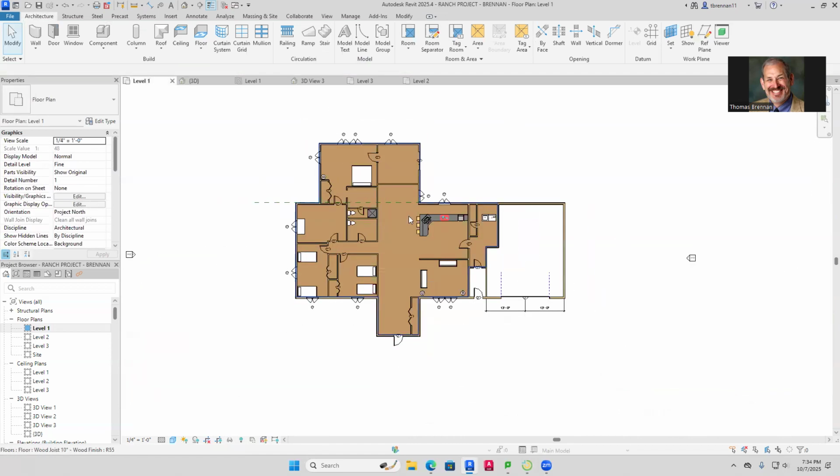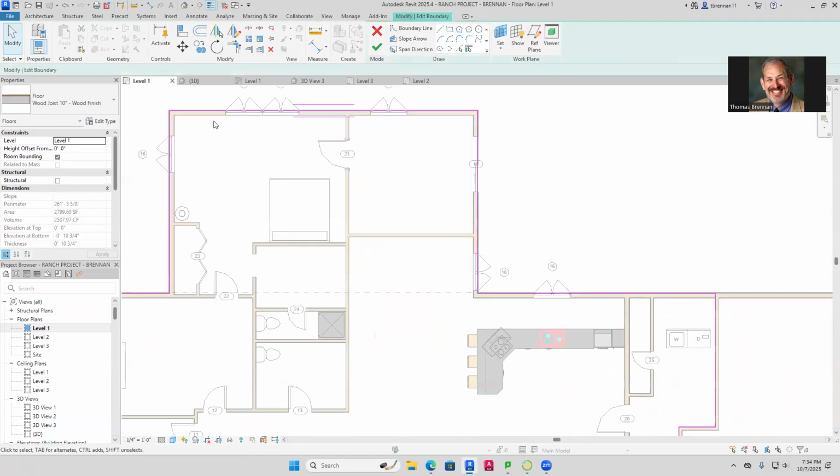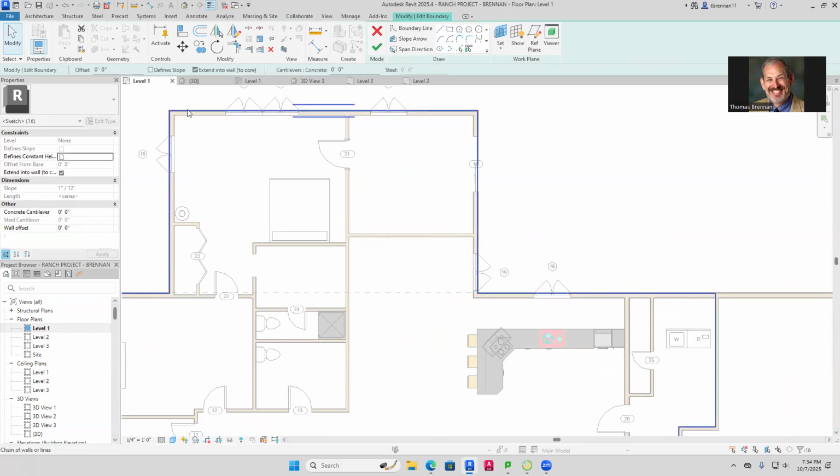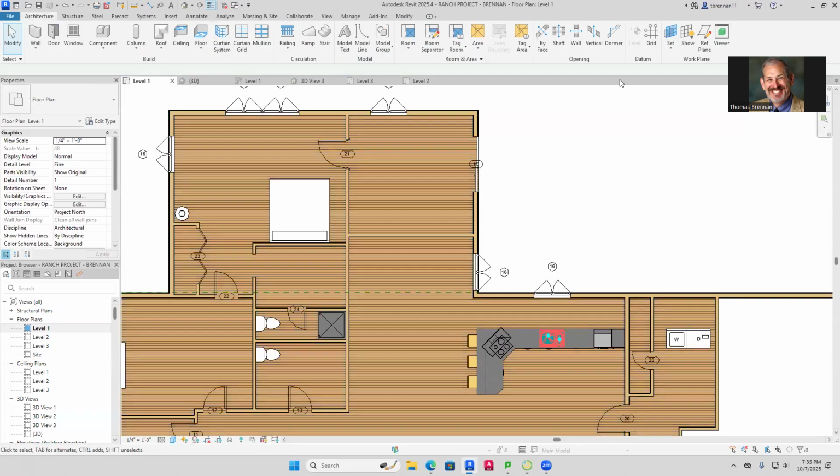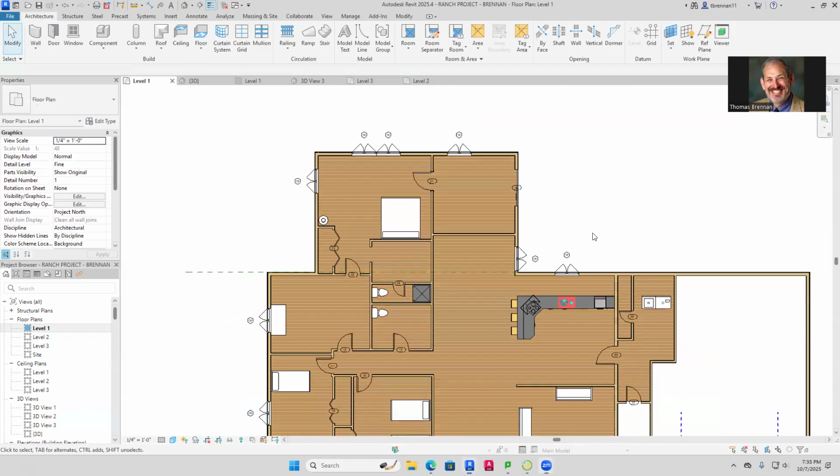Let's see. When I save the render to the project and I exit out of it, it goes back to the unrendered version. That's not how it's supposed to go, right? When you save a rendered version, you want to save it to your project, and then look in your project browser under renderings. It'll be under renderings, and you'll see it in there. Got it? Good.